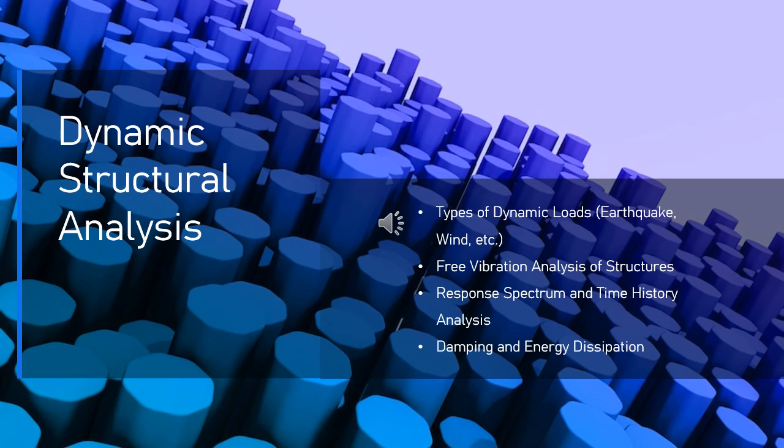9.2. Wind loads. Wind loads result from the force exerted by the movement of air, typically caused by atmospheric pressure differences. These loads can significantly affect buildings, towers, bridges, and other tall structures. Characteristics of wind loads. Time varying. Wind speed and direction change with time, creating fluctuating forces on structures. This variation can be periodic or non-periodic, depending on factors like weather conditions and topography.